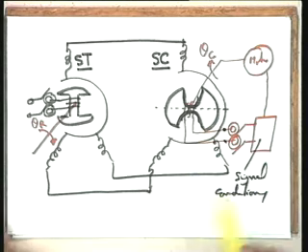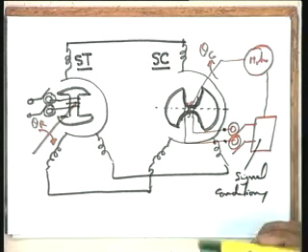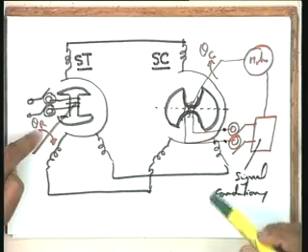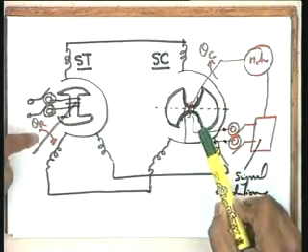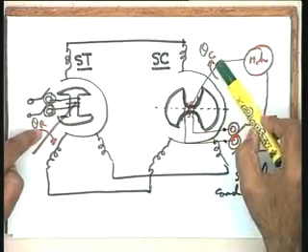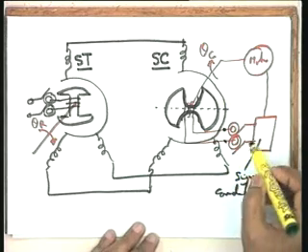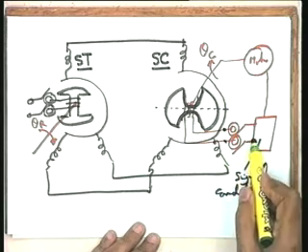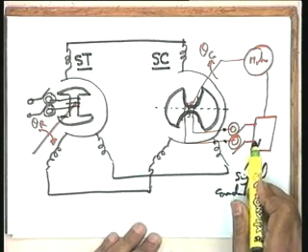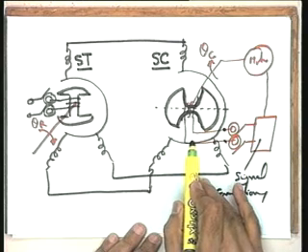And the objective in this particular case, the input and output, you see, what is the input? The input in this particular case is the deviation of the two shafts, theta r and theta c, and the output is the output voltage available across the rotor terminals of the control transformer here.